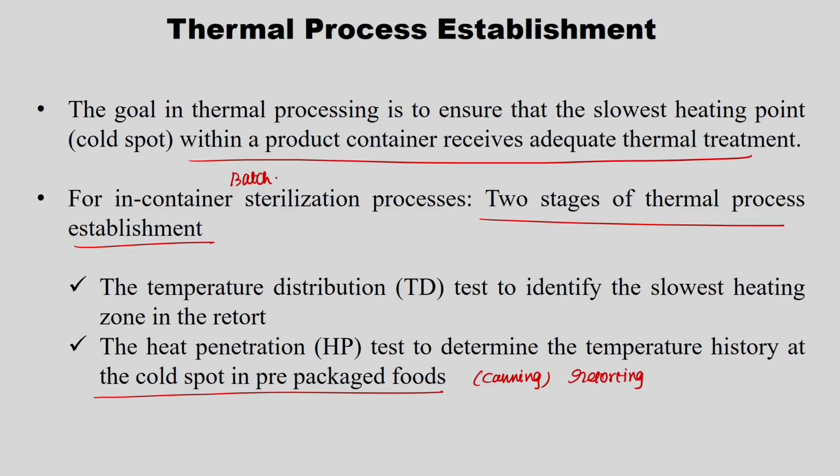But why did we specify especially in-container sterilization? For inline sterilization you may not require the temperature distribution test, because the heat is given directly to the product. So, you would like to have the heat penetration test only. This may not be required, but it is in addition to the heat penetration test you would like to have, but that is not necessary.